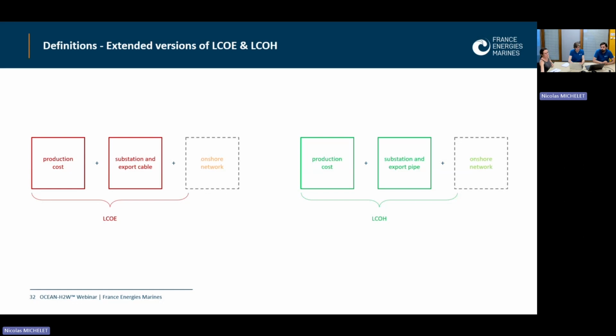Yes, exactly. With time, the electrolyzer inside the simulation loses efficiency, and once we have crossed a certain threshold, we consider that we change the stack of the electrolyzer, and then the tool includes this new stack inside the capital expenditure of the whole project. So, for example, for the case I showed you, in 20 years, we have 3 changes of the stack, if I remember well, which were accounted inside the whole expenditure of the wind farms.